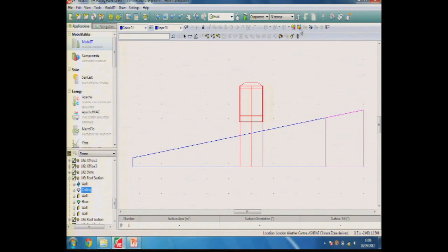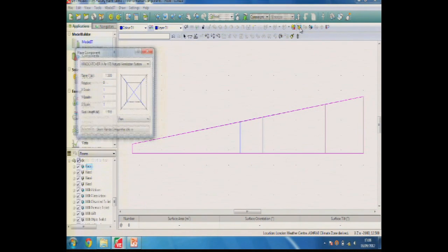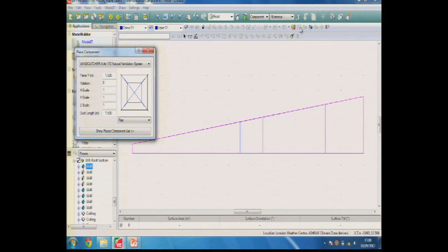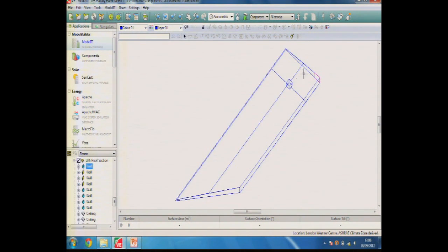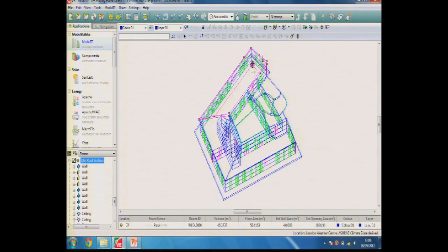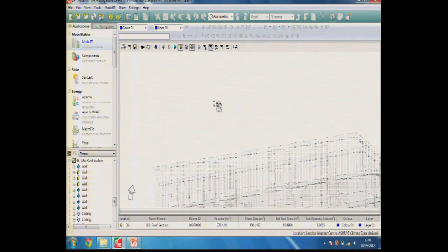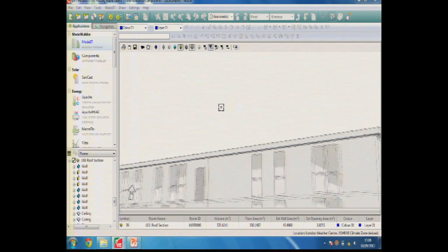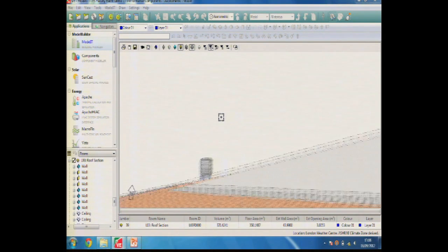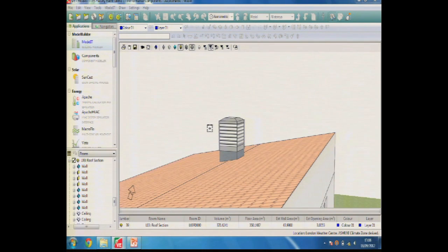If I then select that component and click on this new icon here, Finalize Component, that subtracts the geometry of the model that intersects with the component, and the component itself then becomes part of the geometry of the model. So we can see, going on to axonometric view there, the area that's been subtracted, and this Windcatcher now forms part of the model, so it's its own zone in its own right. If I fly up over here, we can see we have the Windcatcher, which has everything predefined. We've got the construction templates, the macro opening profiles, and the textures, so we can visualize the tool.